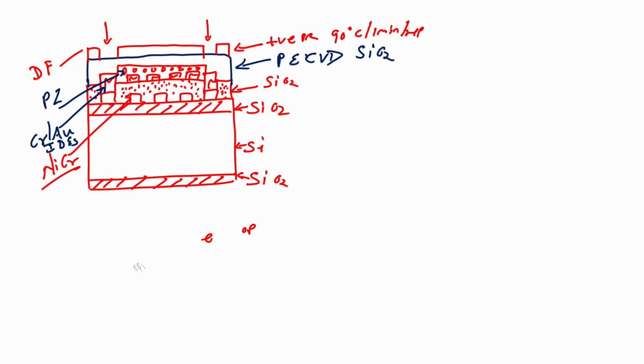Now, what is my goal? My goal is to remove silicon dioxide from the contacts of the interdigitated electrodes and the heater contacts. So, the next step after this would be to do the hard bake. It is assumed that whenever you use photoresist, you have to do soft bake and hard bake. However, I will try not to miss it, so do not worry.